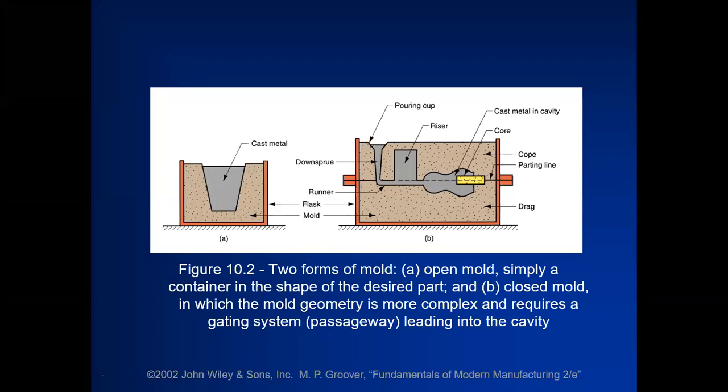Yes sir. Okay, good. So what we have to do is design the passageway or gating system in such a way that the flow should be maintained. Laminar, sir. Laminar flow. Okay, then it comes toward the riser.